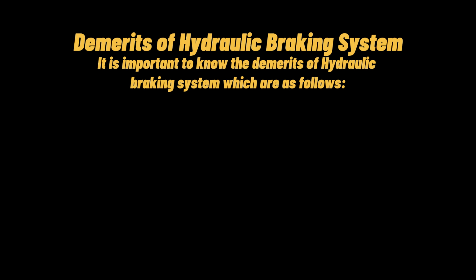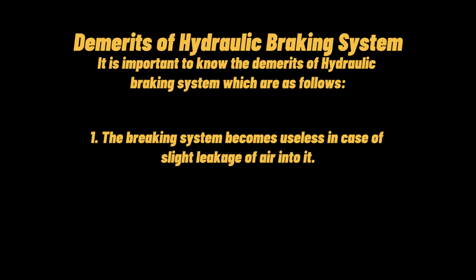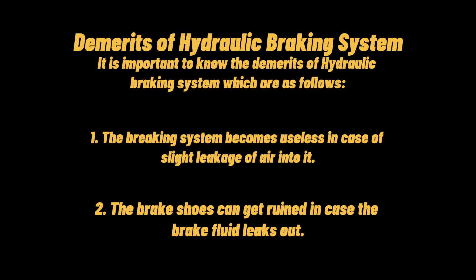Demerits of hydraulic braking system. It is important to know the demerits of hydraulic braking system, which are as follows. 1. The braking system becomes useless in case of slight leakage of air into it. 2. The brake shoes can get ruined in case the brake fluid leaks out.